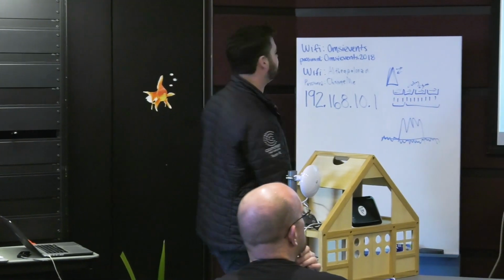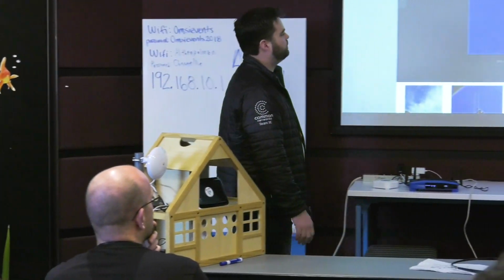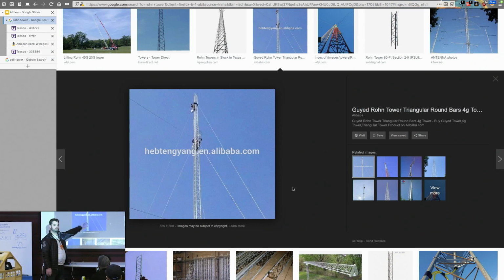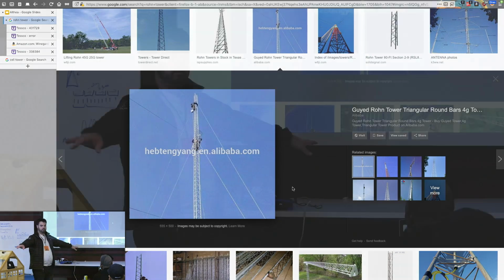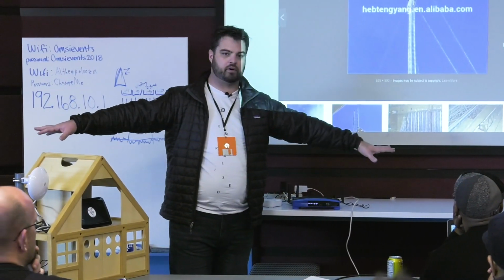let's see if any of these have good examples. Yeah, oh yeah, that is a good one. So these wires you see coming off, those are guy wires. They are attached to the tower and then also anchored some distance away from the tower. Usually there's 3 coming off the tower, and then each of them are tightened. And if you have the physical space to be able to put those, because often they need to go pretty far away from the tower.